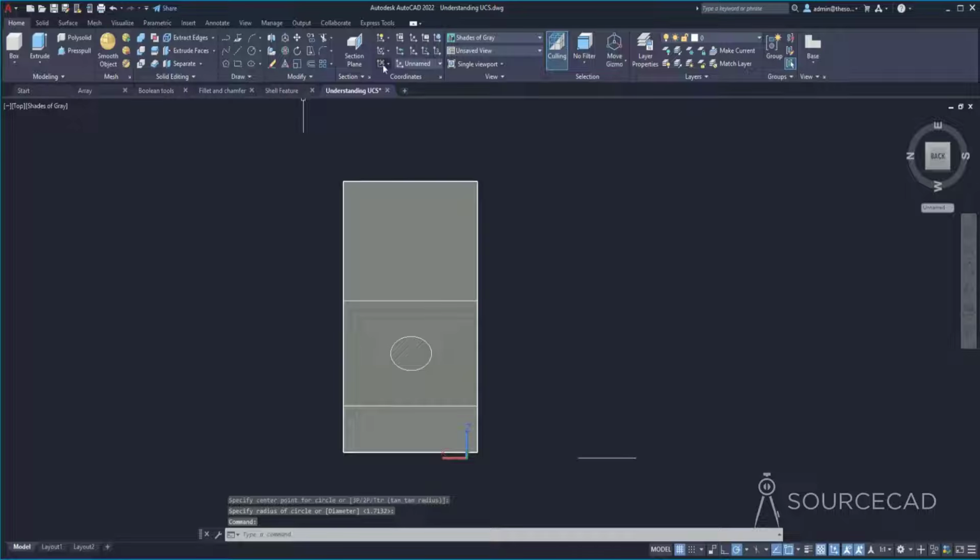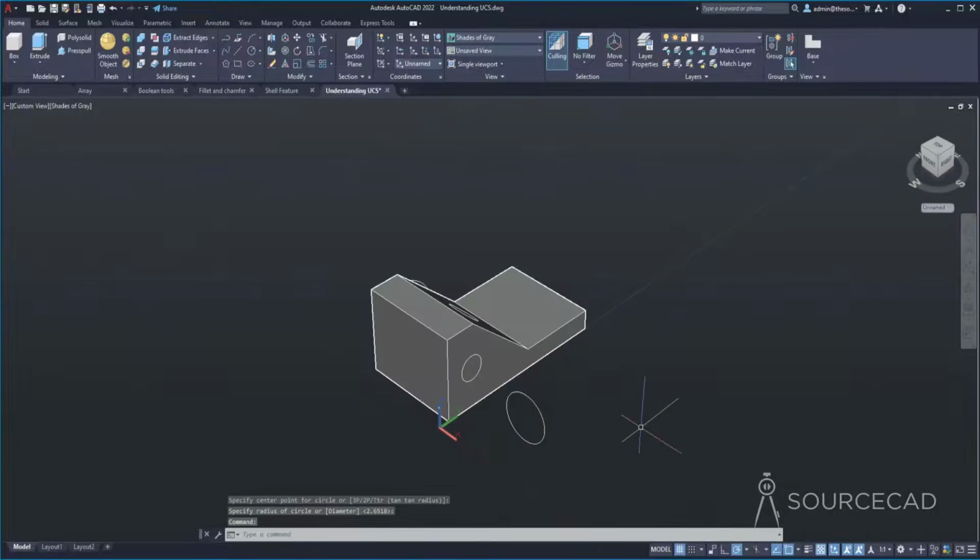Once again, you can switch to any other view, for example, this one. Now just go to this coordinates view option, and now this is XY. So once again, we can make our drawing in this one. Once you are done making all these changes, you can simply click on World UCS to return back to the default location of UCS.